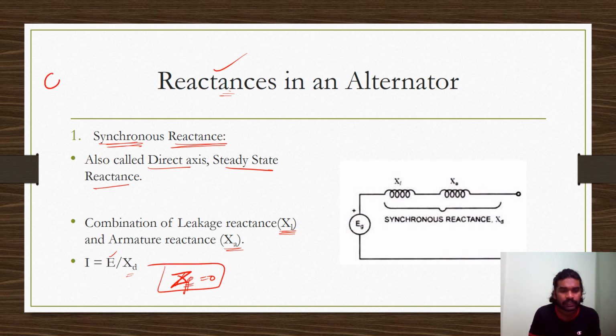See, we have already seen this is the Thevenin equivalent of that circuit, and say a fault has occurred at this point. The fault occurs at this point, but by occurring, it has also introduced some reactance or impedance Xf, and this is the already existing Xd in the system, and this is the internal voltage of your generator. Now what happens due to the occurrence of fault?